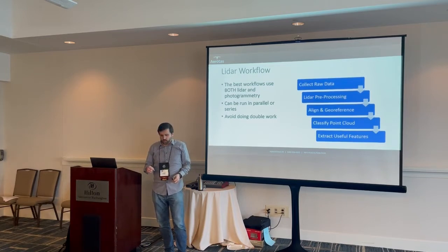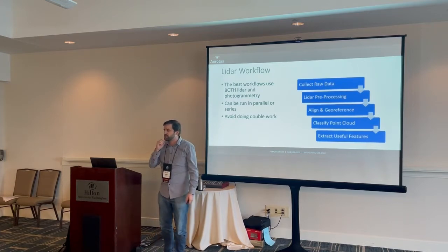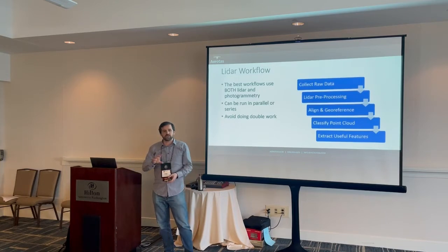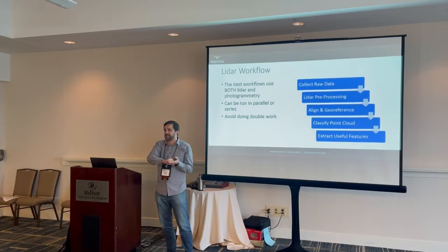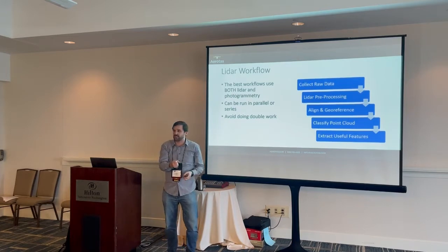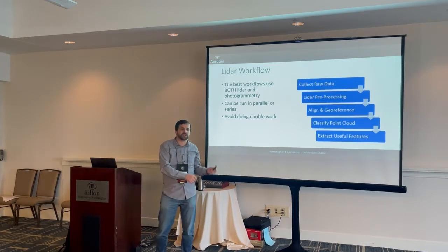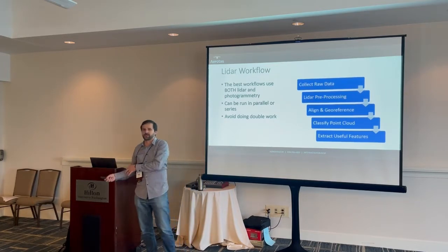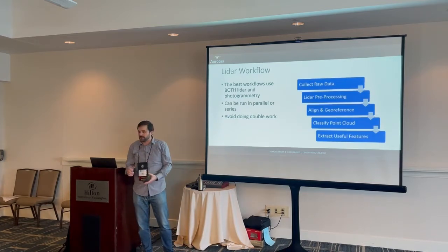Because a LiDAR sensor just measures the distance from the sensor to the ground. It does that a couple hundred thousand times a second. But you need to add that to the GPS data, where the drone was when it took that distance, the angle of the LiDAR sensor, the angle of the gimbal, and you need to process that, and then you need to apply a coordinate system to it. Are you doing this in WGS84, NAD83, are you using ellipsoidal height, geoidal height, all of that, before you actually get to a point cloud.